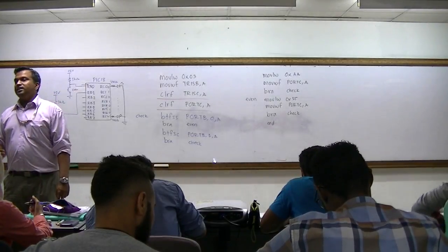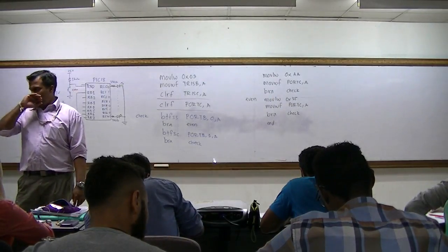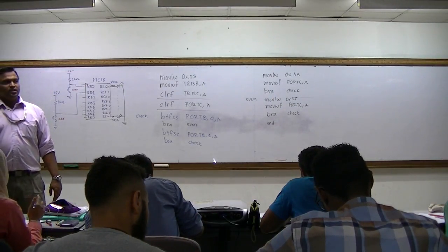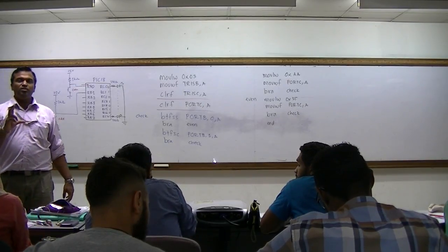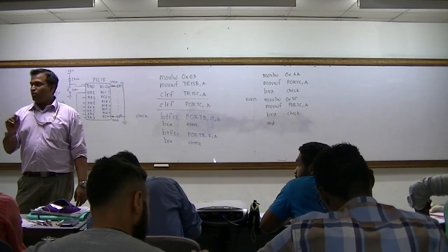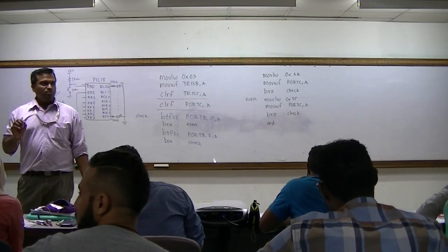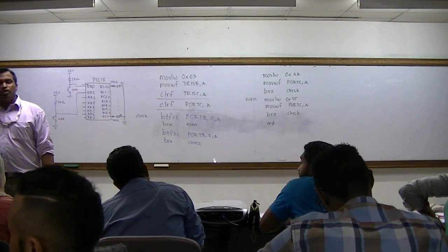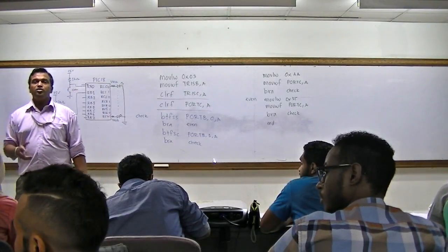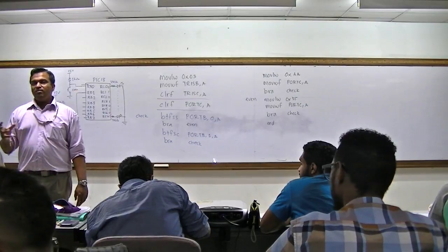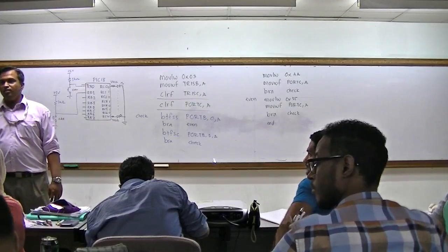And then we studied the interfacing with 7 segment. There are 2 types of interfacing with 7 segment. One, you need to use the buffer IC of course, and you connect each pin of the 7 segment to 7 pins of the port. In that way you need to find out the value that you need to load into the particular port to display the character. The second one is much easier because it's using the BCD encoder. Whatever value that you want to display, straight away just load that value in hex and move it to that port and you can have it.